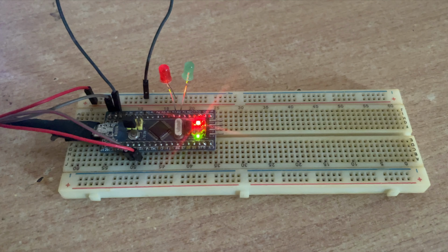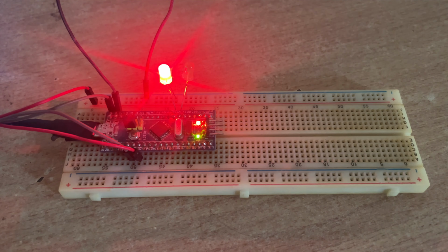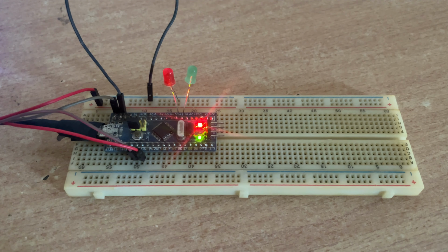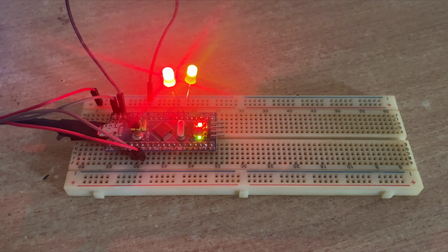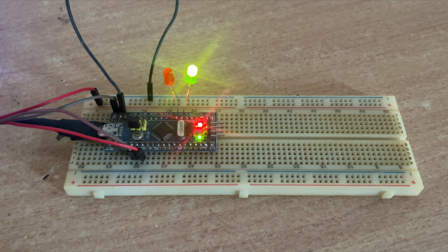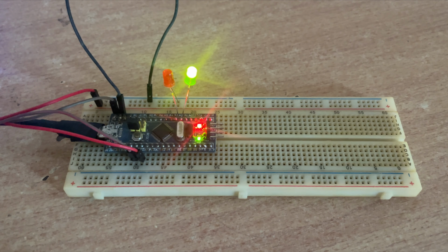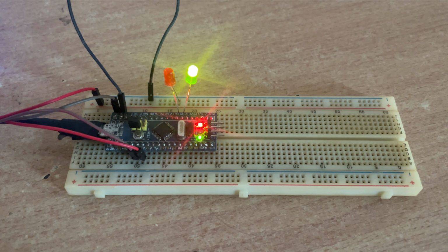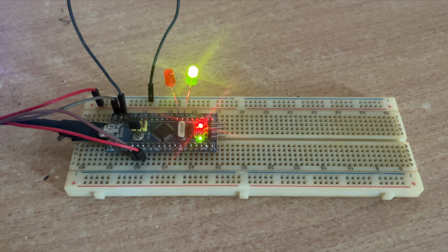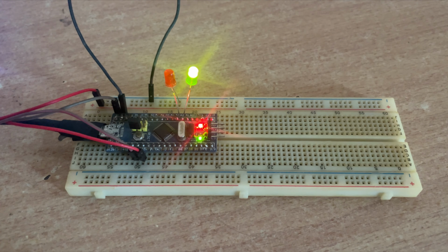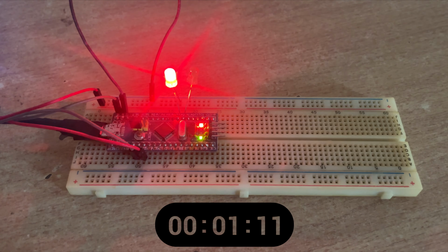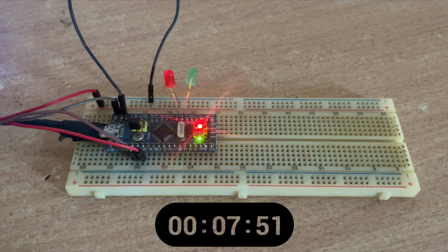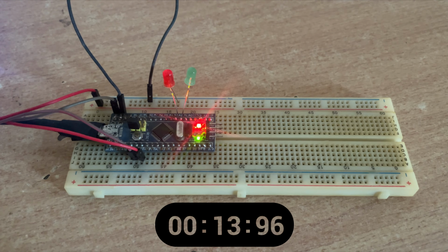You can see the red LED blinking twice. This indicates the MCU is about to enter stop mode. Now, every time the green LED toggles, that means the RTC alarm has triggered and the MCU has woken up. What you're seeing here is one complete cycle. Wake up from RTC, green LED toggle, red LED blinks twice, back to stop mode, and this cycle should repeat every 15 seconds, if the clock is accurate.